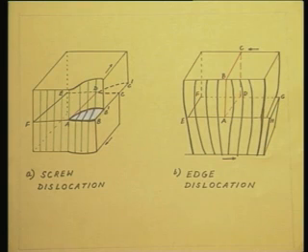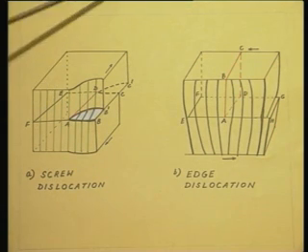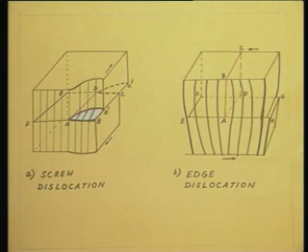Think of this plane A, B, C, D. Imagine that the crystal is cut along this plane, and then you are subjecting it to shear stress on both sides of this plane A, B, C, D, top and bottom. You are trying to force the top half like this and the bottom half like this. So, what will happen? What will happen is seen in this white highlighted area.